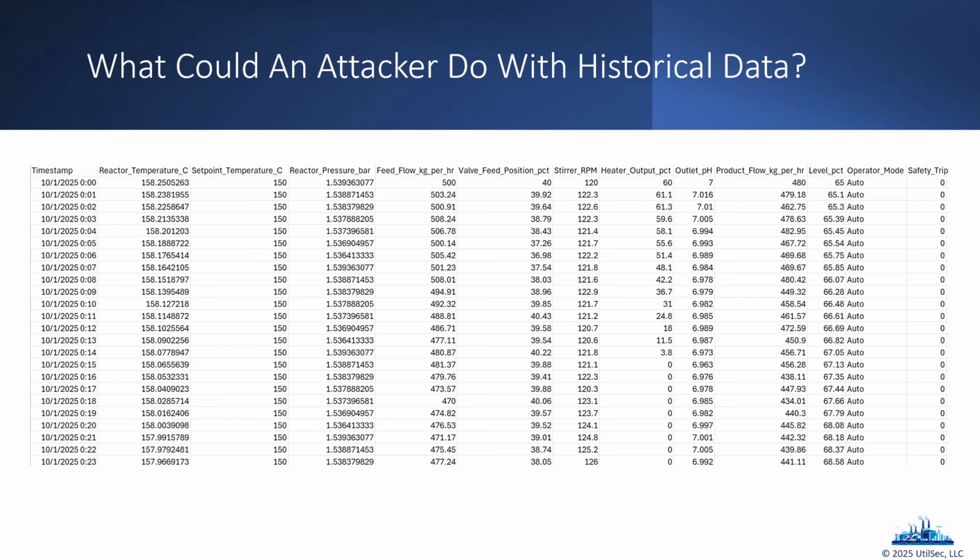There are a couple of things that we see from the data historian perspective. What I'm always looking for is that top row, those tag names. Remember, the tag name can give us the intuitive name to tell us what we're actually looking at. Like when I see a value like 1.53936, what's that? Oh, okay, that's the barometric pressure in this reactor vessel. It even tells us there's a reactor vessel in this environment.